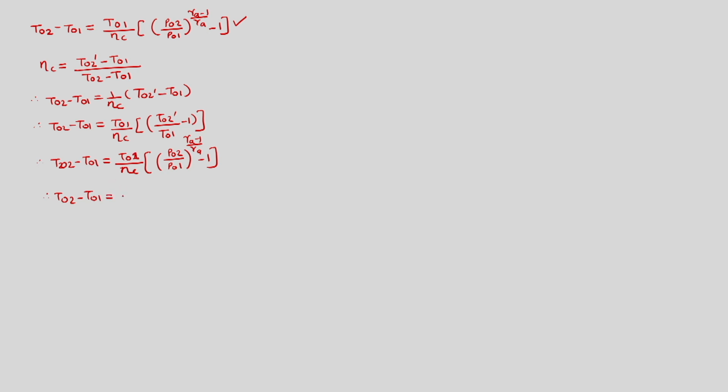is equal to 239.37 divided by 85% compressor efficiency, so into (6 bracket raised to 0.286 minus 1).